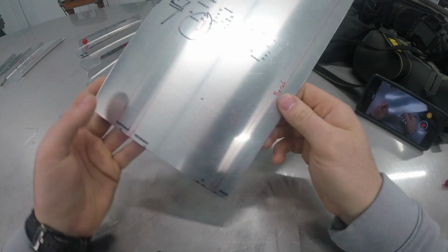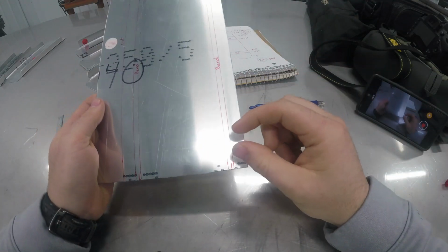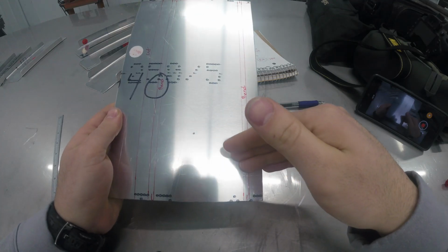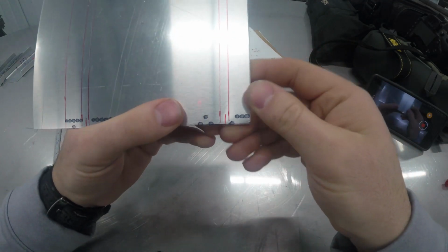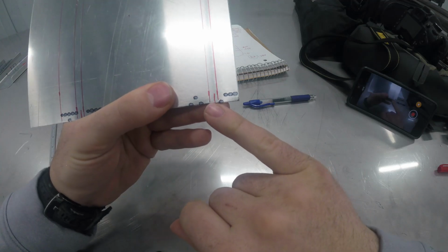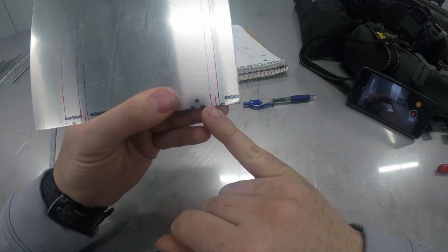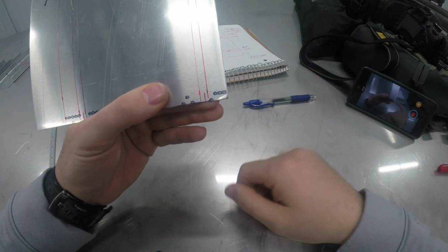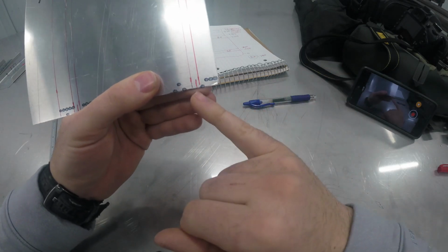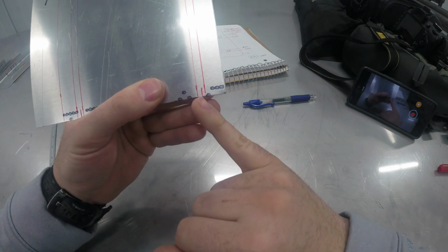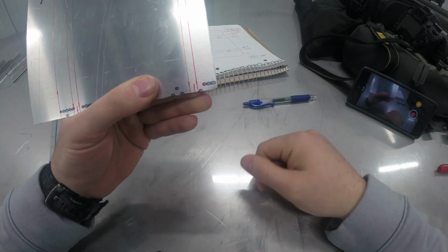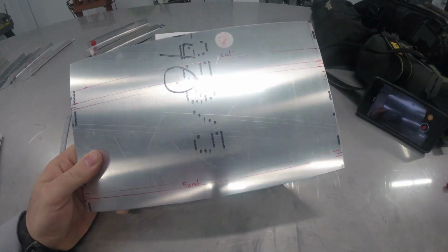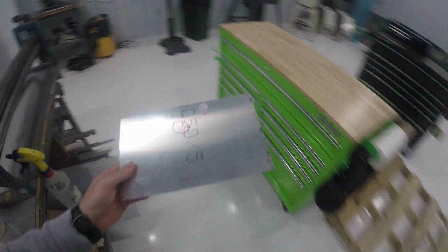One thing we didn't talk about is our sight line. So your sight line is going to be right where your brake sits onto your sheet metal, and that's called our sight line. So you can see I have this mark kind of right in the center of our bend lines. So there's a calculation for this, but for this small of a bend, it's so minuscule, it really doesn't matter. So I usually just eyeball kind of halfway between our bend allowances. So with that, we'll go ahead and go over to the sheet metal shear.